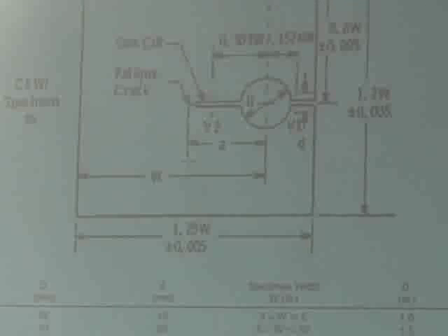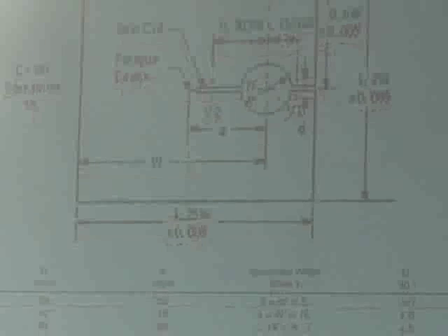It's not a big deal. I mean, you can deal with it, but I'll tell you, it's harder to get R curve data than K data because it's varying on thickness. So it does involve more testing, and the likelihood you find exactly the thickness you're looking for is not necessarily obvious. The good news is when you're dealing with something thin, you don't have to worry as much about the leak before break type situation.